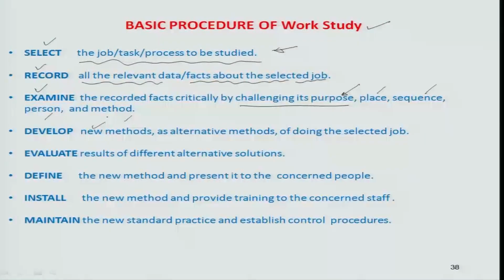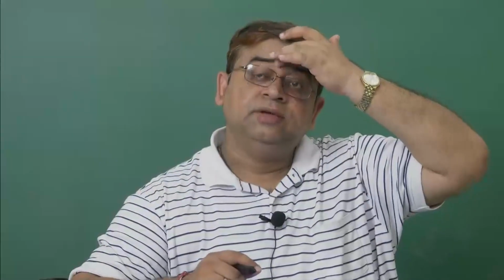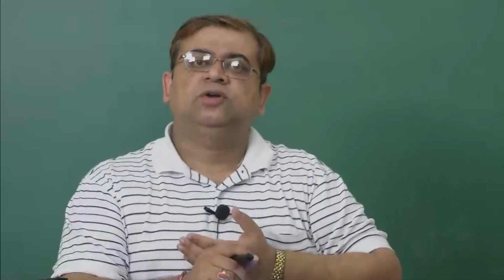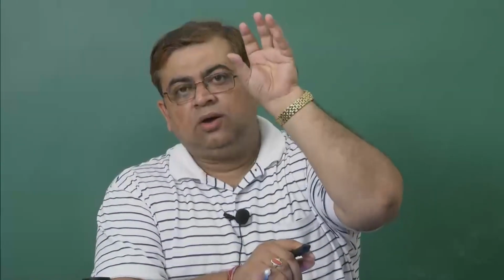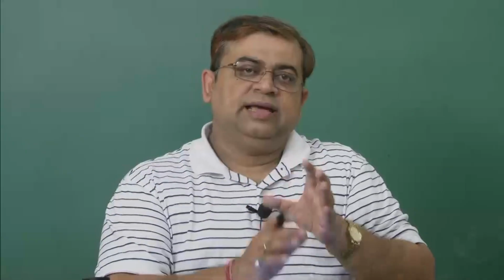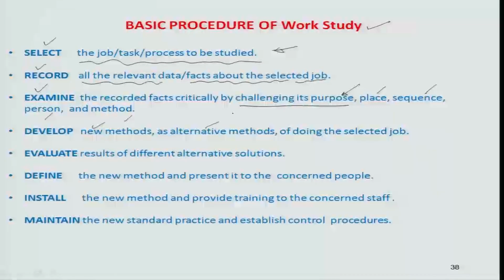For example, looking at a certain task structure, you can say that, okay, this task structure seems to be very wasteful, let us develop an alternative structure like this, where there is some difference between the previous task structure and the newly developed task structure in terms of reduction of wasteful motions, or even reduction of time scales associated with the overall task, etc. And so this new alternative, if it works out well, can be treated as a standard job description or process description for that particular task. And in this manner, for all the 100,000 tasks or more, you develop such alternate methods.